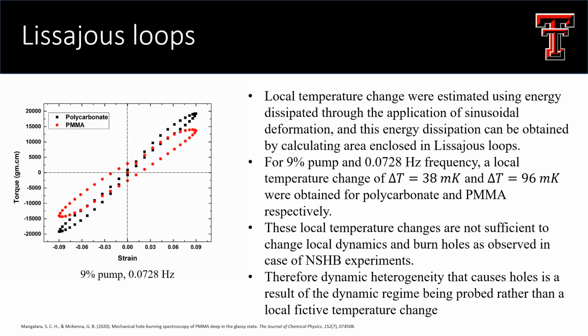In this work, we estimate the local temperature change caused by application of sinusoidal pump deformation by calculating the area enclosed in Lissajous loops. For a 9% pump amplitude and 0.0728 Hz frequency, local temperature changes of 38 millikelvins and 96 millikelvins were obtained for polycarbonate and PMMA respectively.